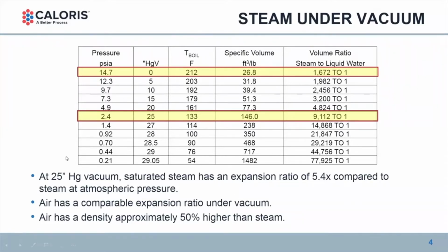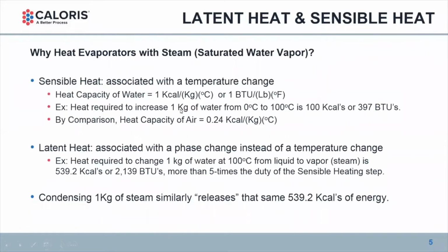I also make the point here that air is a denser gas than steam. You'll hear me using the terms non-condensable gases and air throughout my talk, and I will tend to use those interchangeably. Non-condensable gases are principally oxygen and nitrogen, the principal components of air. Steam is a gas which can condense. Air does not, in our normal operating conditions. The third term that I just want to review here is the difference between sensible heat and latent heat.